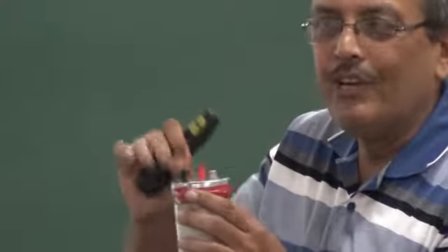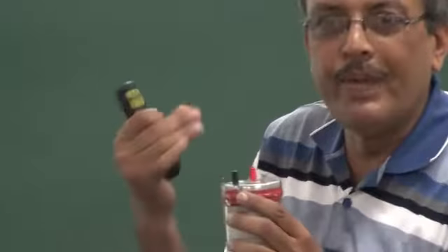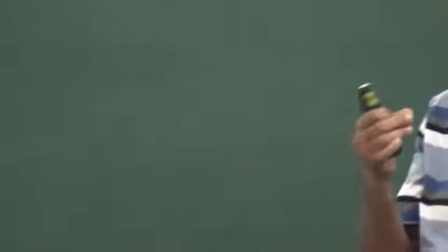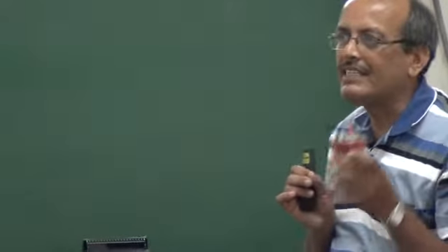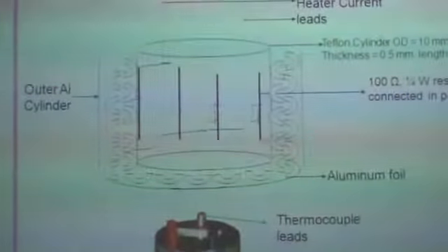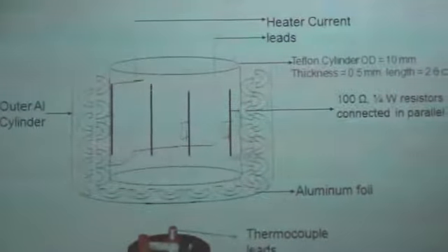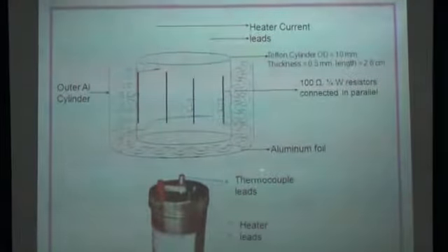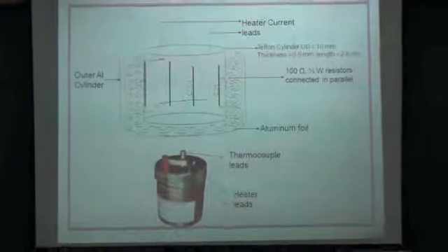Inside, you have to heat the sample and measure the temperature of the sample by using a copper constantan thermocouple. So that is what you see on the top of this box. Then after this, this is how your box looks like. The same thing: this is the thermocouple RCA socket, and these 2 are heater leads.